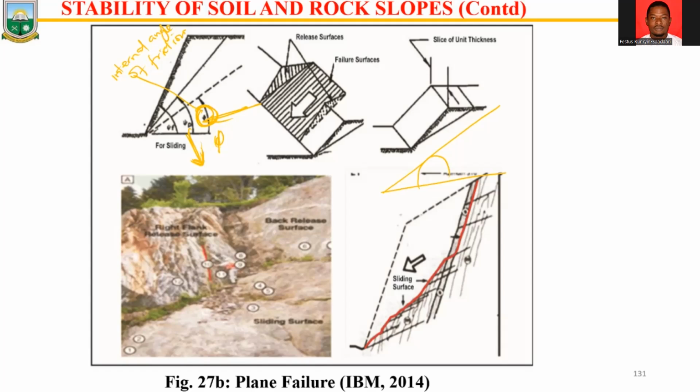Okay, we have talked about the various angles that must be satisfied in order for a failure to occur, or that type of failure that will occur on a slope. We can say it is a planar failure. So assuming you are a geotechnical person, you had your angle of internal friction, which you established from your triaxial test in the laboratory. So you know that already.